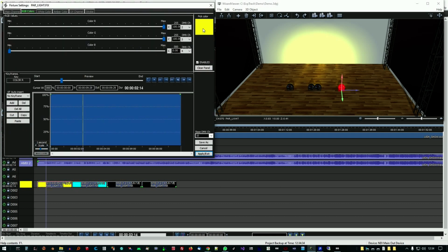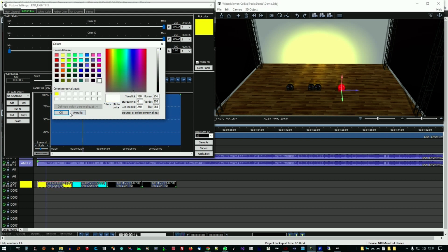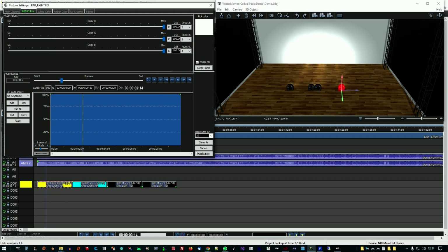If we have a group of fixtures that we will always use as a single lighting element, we could also assign the same basic DMX channel to all the fixtures. In this way, we could create a single group to illuminate the background or areas globally, simplifying programming but limiting the separate use of those lights.